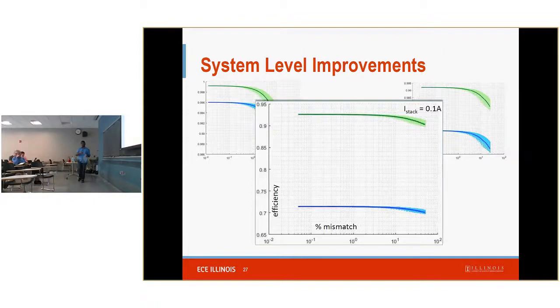But here, the only thing you can do is use level shifters, which are not that fast yet, or you can use optical communication, which is also like 5-10 years from now. Although TI is building a lot of new digital isolators now, because there are ground bounce issues in all these systems anyway. So they're having to isolate the communication across these things. We take advantage of it.